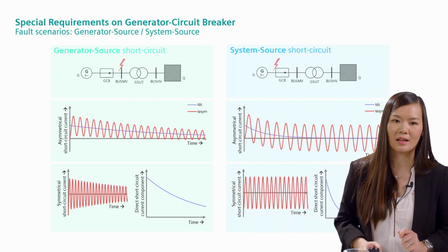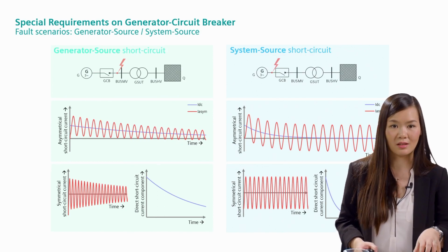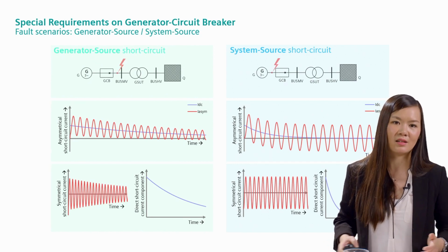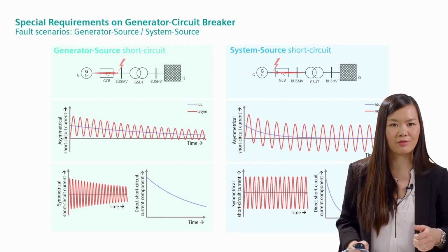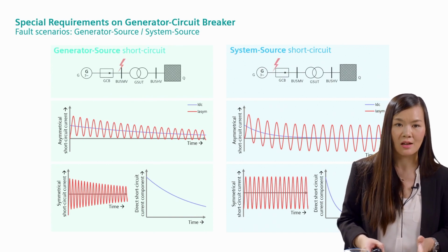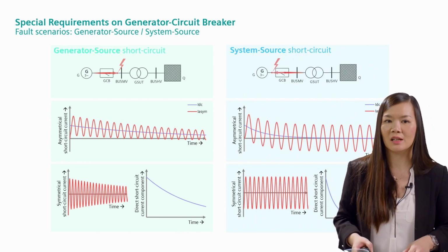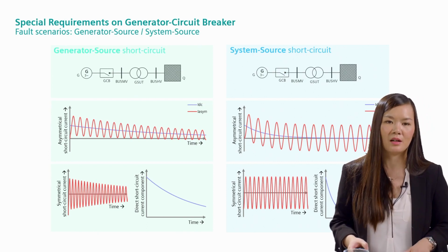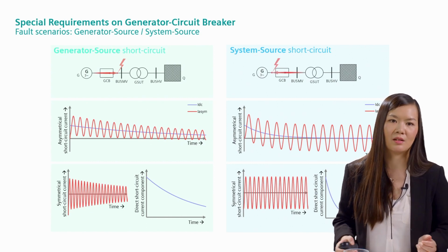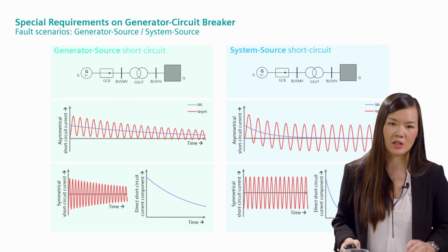And then secondly, a synchronous generator doesn't have only the main winding as a transformer. Depending on the design and the manufacturer, you can have the field winding, because we need an excitation for a synchronous machine. And third, there might be a damper winding, depending on how the design looks. You might need that for the mechanical stability of the machine itself.